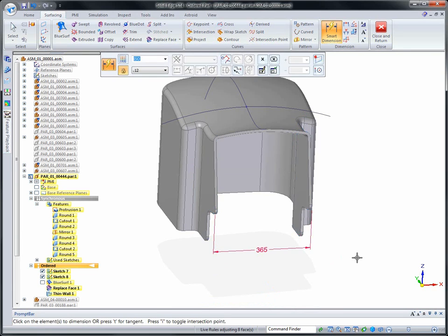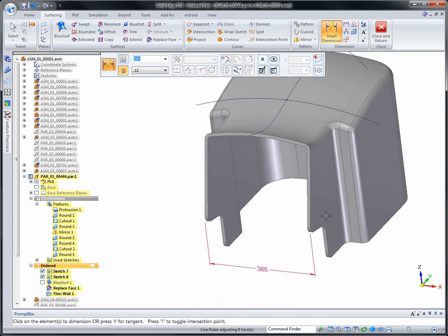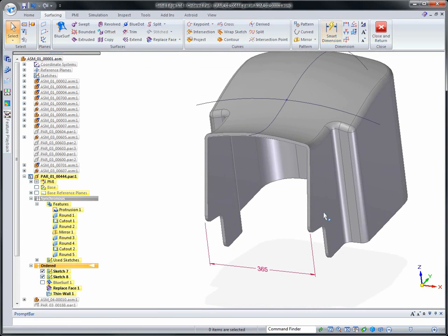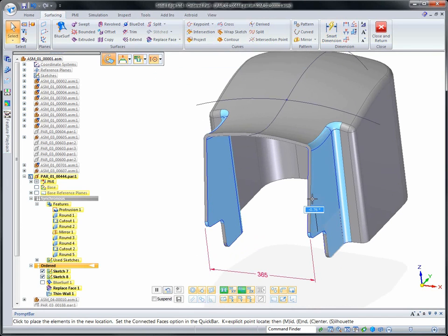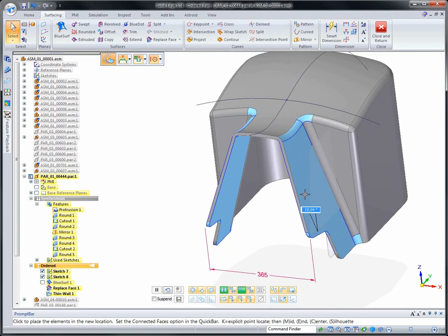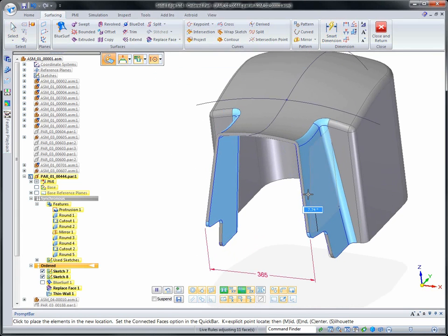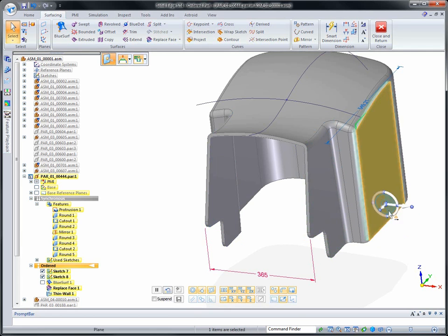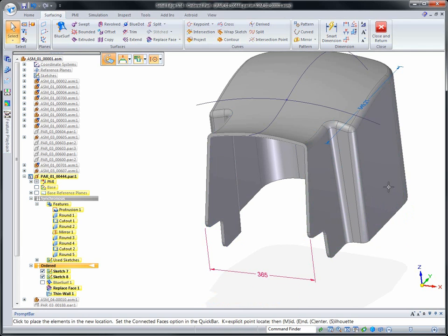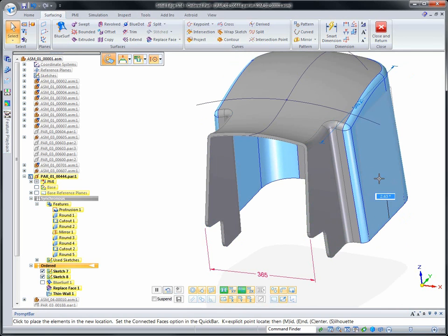You can also lock dimensions so that changes made from the outside with a push or a pull don't change that dimension. Here we're going to add an angle, or add some draft, to the front of this engine cover. Just by rotating the face, you can see that it remains symmetric based on Live Rules. We'll also add that same angle to the sides of the engine cover.